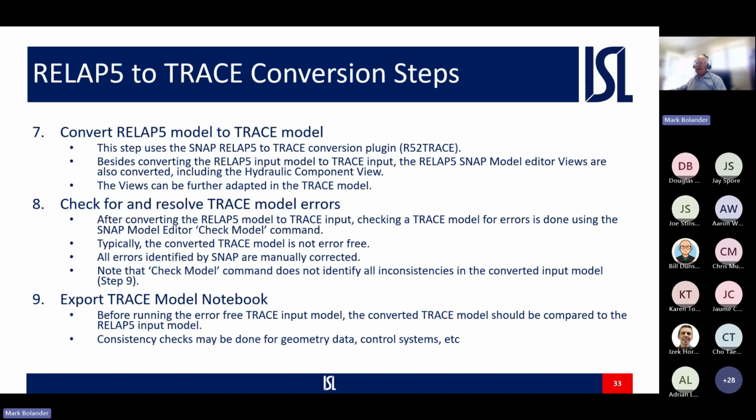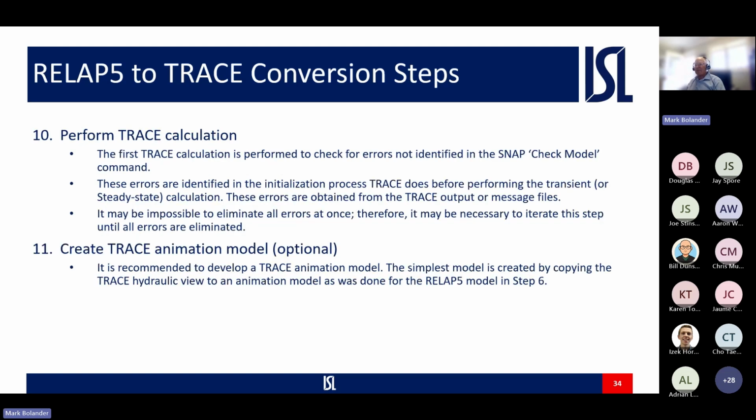So once you get your model converted over to TRACE, it's a good idea to export the model notebook. It's useful in helping to compare with your RELAP5 model notebook, and it helps you find inconsistencies between the two models. You look for that in your geometry, control systems, and so forth, things like that.